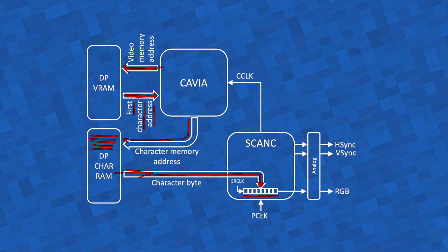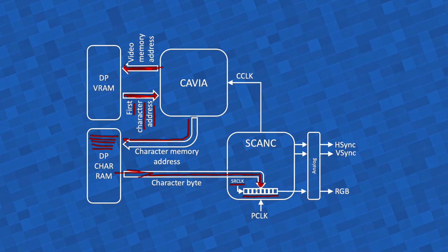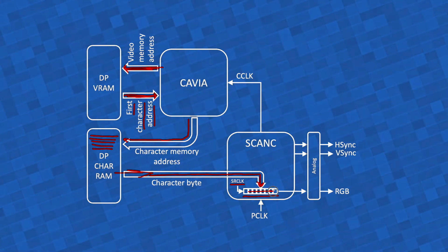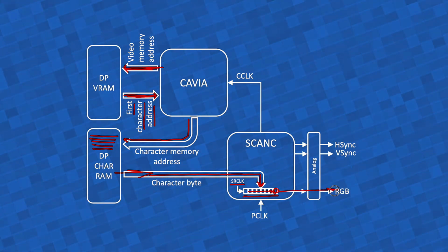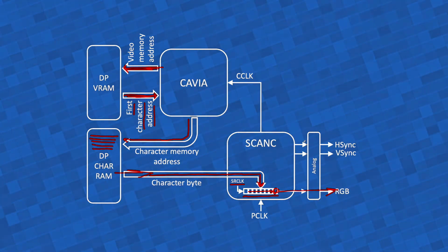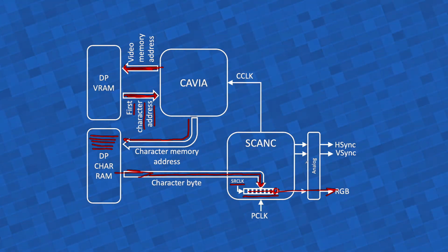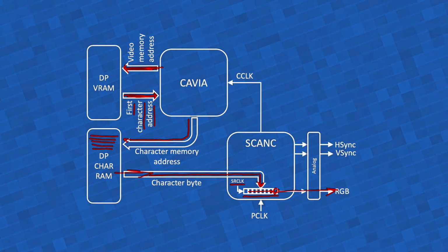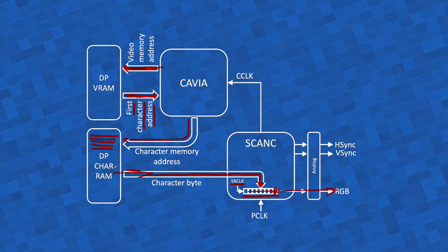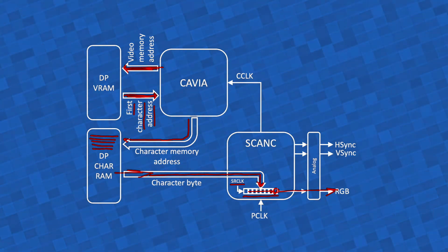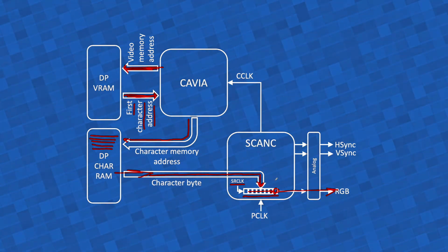After they are loaded, the shift register clock will clock 8 times, moving the contents to the right, such that each bit of that byte will be presented to the television here in the RGB signal after it passes some analog circuitry. That's very simple, just some voltage dividers and some buffers. So that's how it works. Once all 8 bits are shifted out, then the next byte will come in and be parallel loaded into the shift register, and they will be shifted out again, and the process will continue this way.